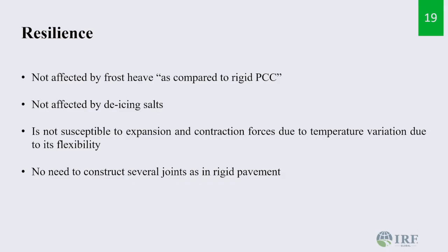Now the asphalt has high flexibility. It's called flexible pavement. So the amount of cracks, or the minor cracks that develop, will be smaller compared to when you have a rigid pavement. Now that would not be the case in Nigeria, not the case in Egypt. Also, think about rutting. That's what the rigid pavement manufacturers reply. I'm here strictly talking about frost heave, which results in uneven push-up of the pavement. The flexibility of the asphalt makes it a better candidate.